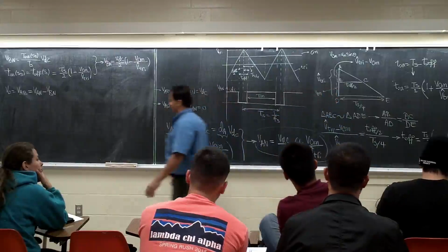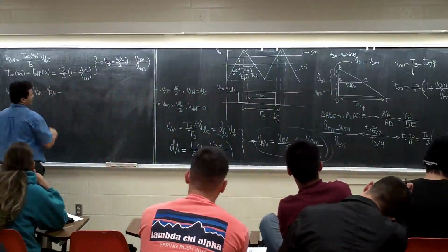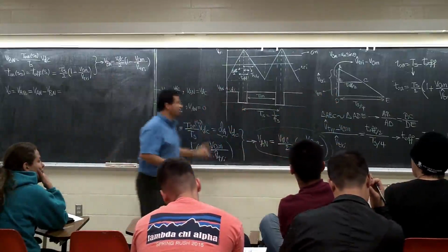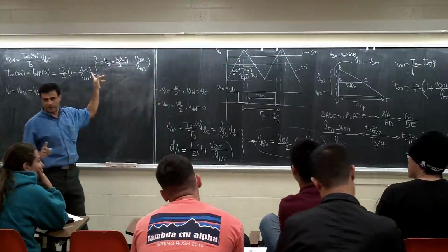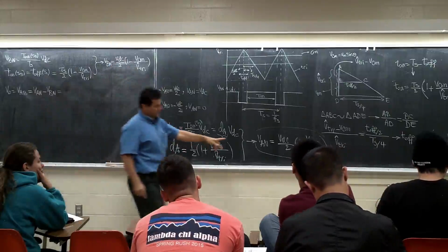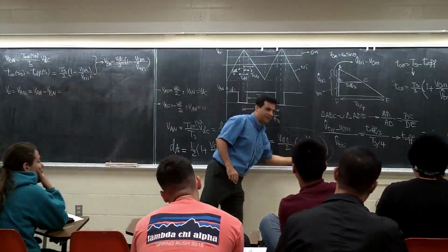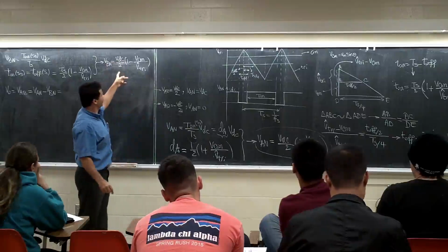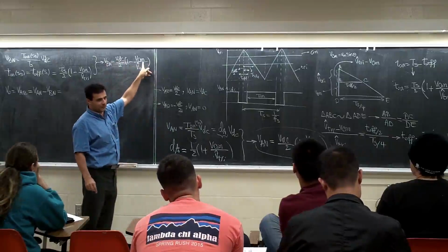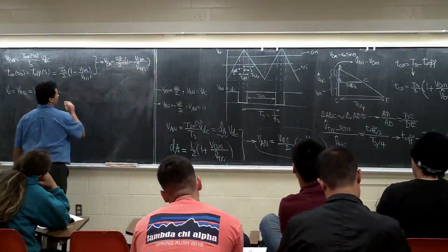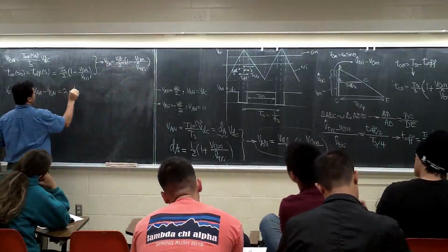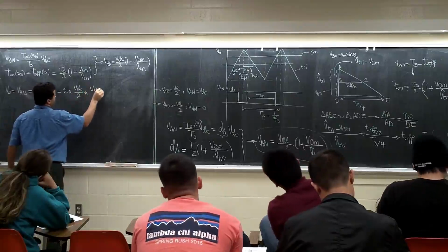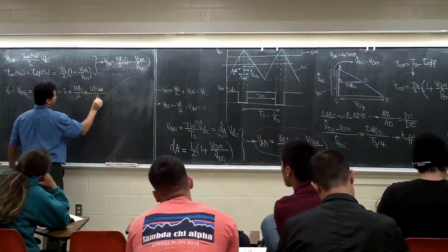So it's going to be VDC over 2 minus VDC over 2. They cancel each other, right? But the next part, VDC over 2 times this minus VDC over 2 times minus this one. Minus and minus is going to be plus, right? So basically it's going to be 2 times VDC over 2 times V con over VTRI.